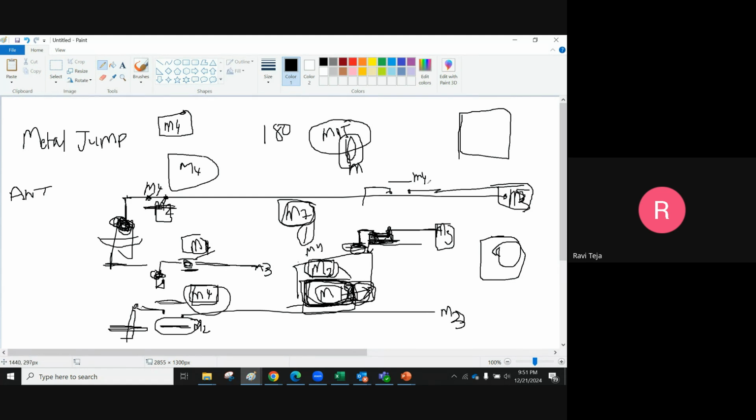Once M3 is fabricated and it is cooled down, now M4 is fabricated. If there is any charge on this, that doesn't matter because it is a small area. And also now there is a closed circuit, but there is no charge on M3, because before fabricating M4, you removed all the charge that was in M3.